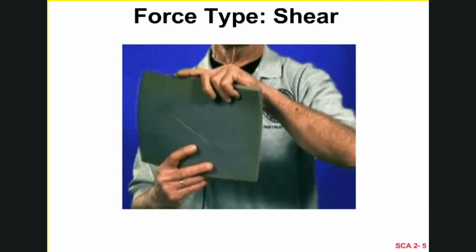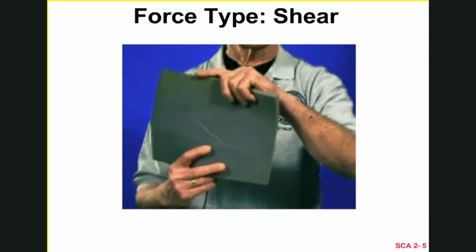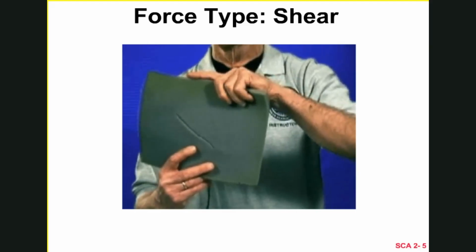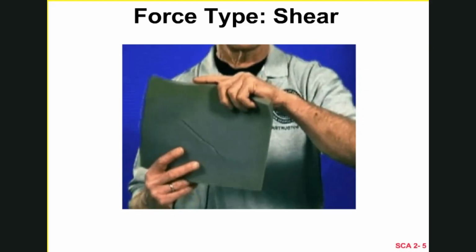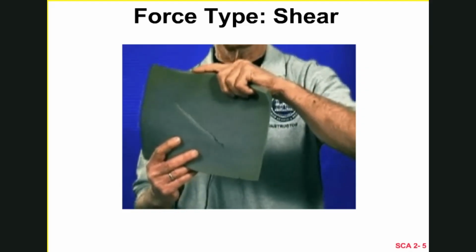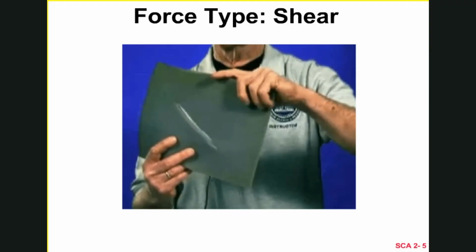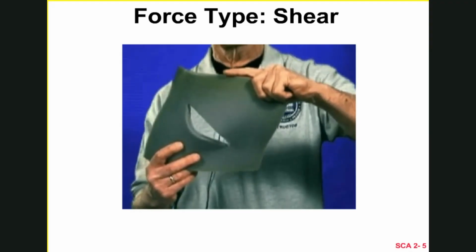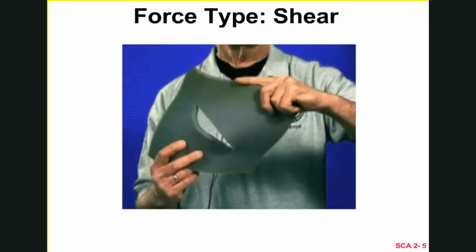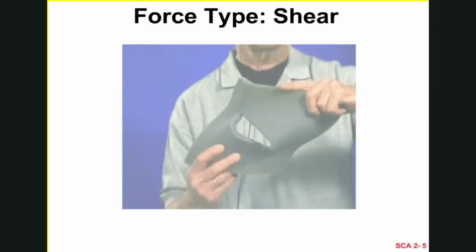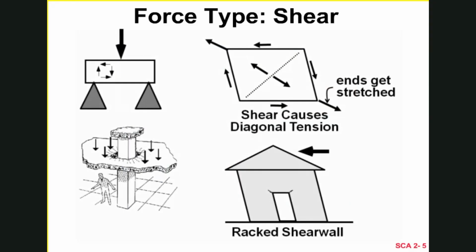And when one is loaded in one direction, going to the left, let's say, you get a crack in one direction. When you turn it around and go to the right, you get a crack in the other direction. And in earthquake damaged structures, what we see is X cracking, and that's where that X cracking comes from. The whole concept of the parallelogramming we call racking of a structure. And we will see in subsequent slides many structures that are racked, and that's a cause for concern, of course, and then some judgments are made about that.